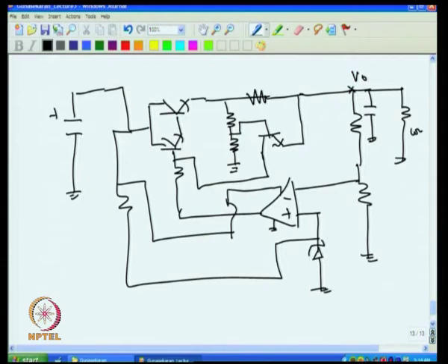Actually we had in the earlier case only this resistance and this transistor for short circuit protection. Now, we added these two resistors extra and terminated the base to the midpoint of this, and once you do this, we will soon see that this circuit gives me the protection in the sense that once short occurs, the current is limited at a lower current. In our earlier example the normal current was 0.6 ampere. Now, I want to limit this to 0.3 ampere. That work is done by this, and that happens because of this voltage divider.